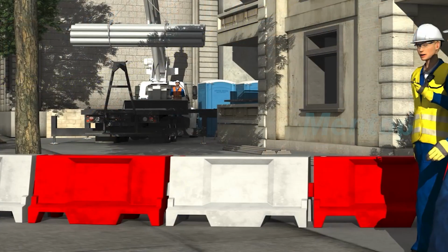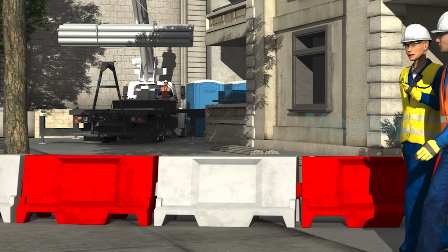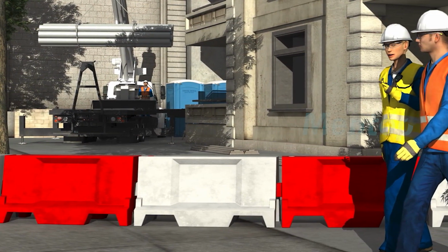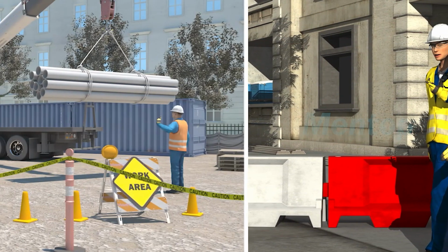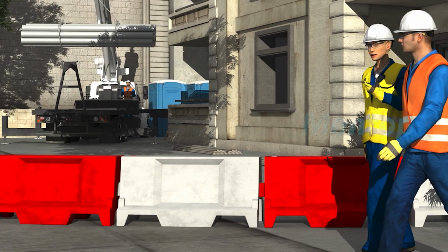Your employer should erect barriers to mark the area covered by the rotating superstructure to warn workers of the danger zone. These could be danger tape warning employees or physical barriers to prevent workers from accessing the danger zone. The barriers should be maintained to ensure they are in the proper position and will prevent employee access.